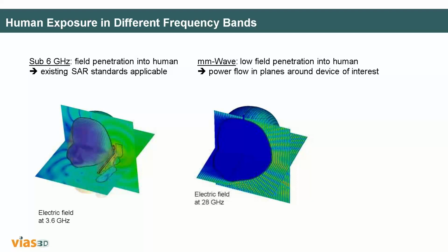Because every antenna is equipped with a dielectric slab, right? That dielectric slab may not withstand that kind of temperature rise. For example, if the temperature is above 200 or 300 degrees Celsius, it can get damaged. And the second thing is that the same temperature rise can accelerate the electrons. Unfortunately, it will not be like the effect in space, where secondary electron emission will be there.